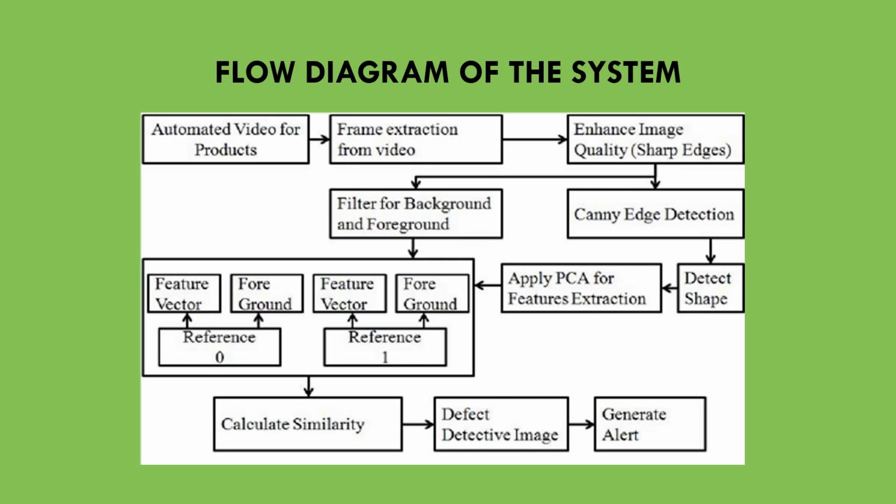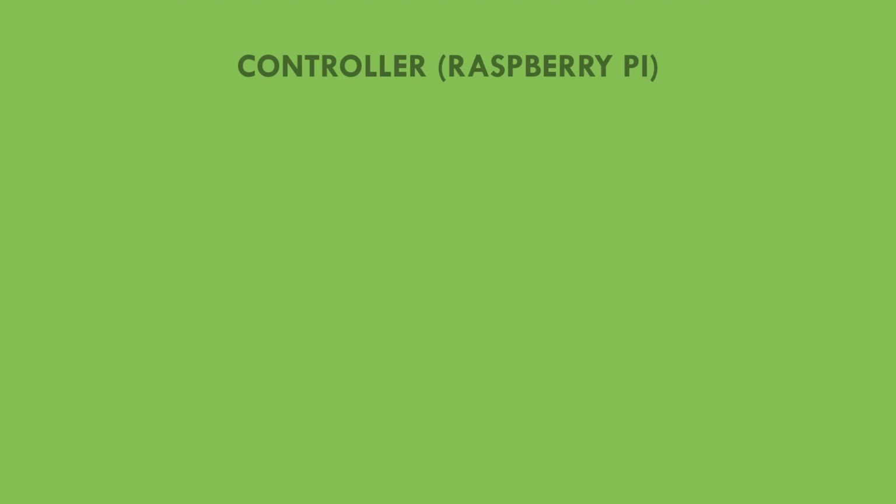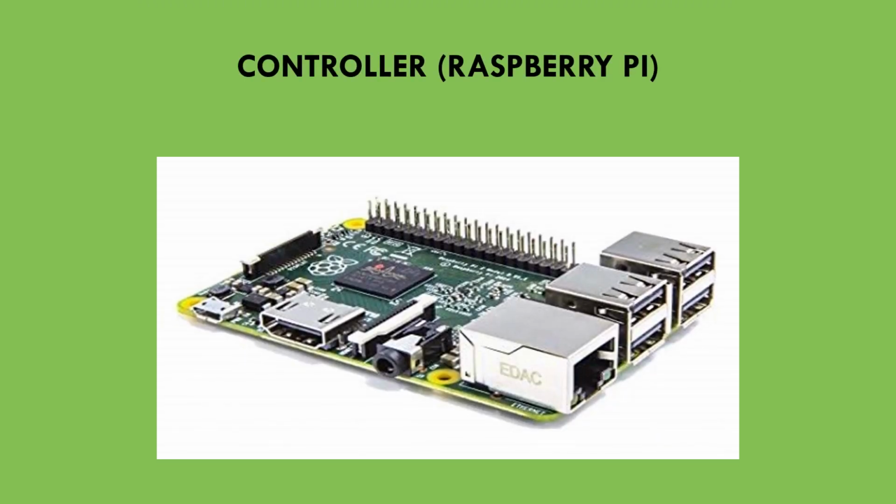High-pass filters will highlight regions with high frequencies. Low-pass filters are used for image smoothing and noise reduction. Their effect is averaging of the existing pixel with the values of its neighbors, apparent as a blurring of the output image, and will allow the low frequencies to pass.